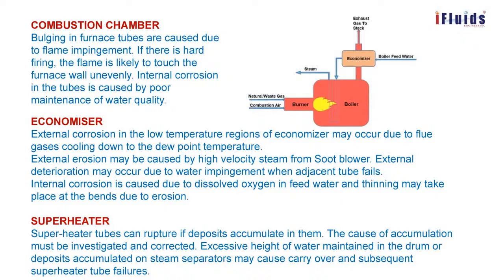If there is hard firing, the flame is likely to touch the furnace wall unevenly. The flame should not touch the furnace tubes, and the combustion chamber also should not be touched by the flame. Internal corrosion in the tube is caused by poor maintenance of water quality.